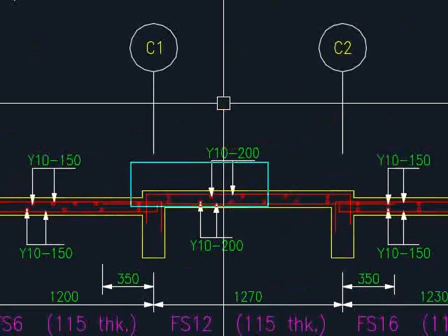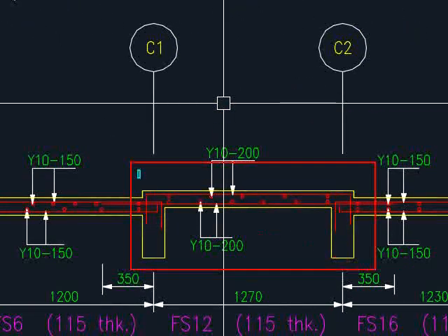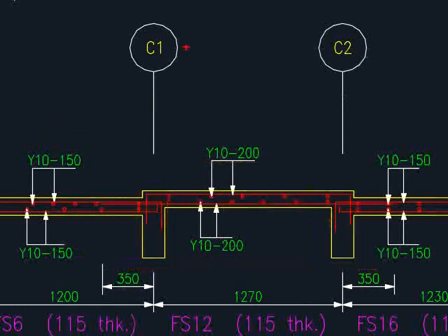This is an example of the slab when the supports are too closely spaced together. If you quantify the required anchorage length, they might clash into each other, or even if they don't clash, the space here will be quite limited. Might as well extend the reinforcement bar to make it continuous on top of the slabs.